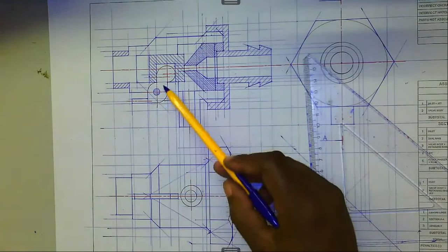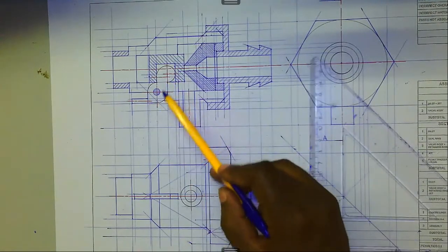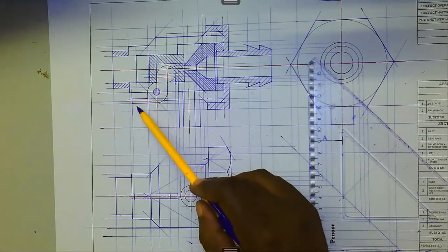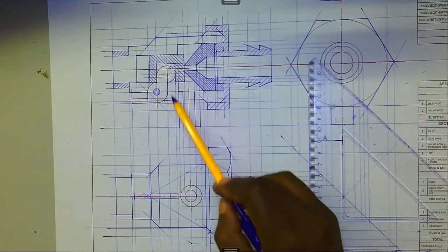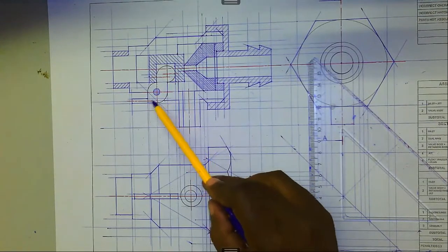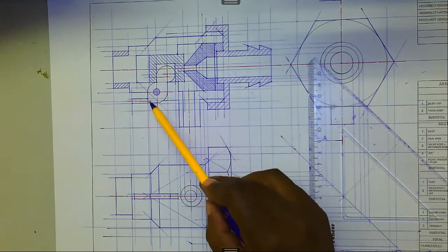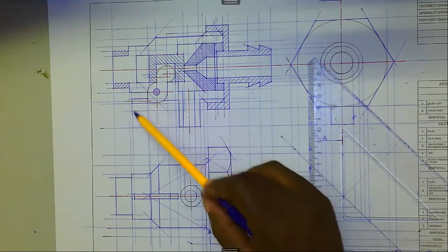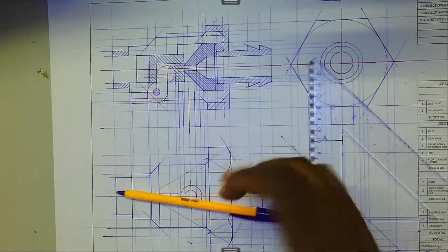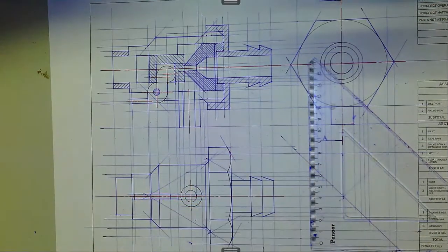The hatching, like I said, you could still hatch that, but you would lose the identity of this part because it would appear as if it's uniform throughout. So to retain that, by showing a center line here and a cross like that, it shows that this part is cylindrical, but the other one is just a piece of material, like a sheet material.